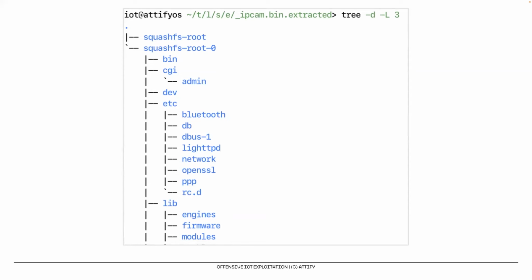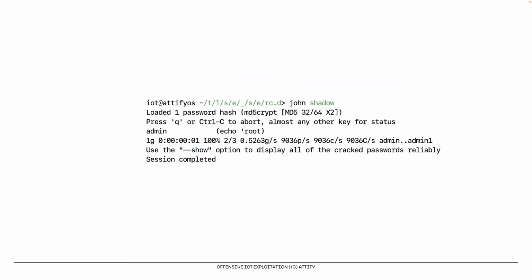And the file system comes from the firmware, which is what you obtain by connecting to the flash chip over SPI. You can also obtain firmware in some cases from the vendor's website, but in many cases, you won't have it publicly available. And also from the file system, you can do things like password cracking and use it as a way to gain access to the device over SSH and so on.